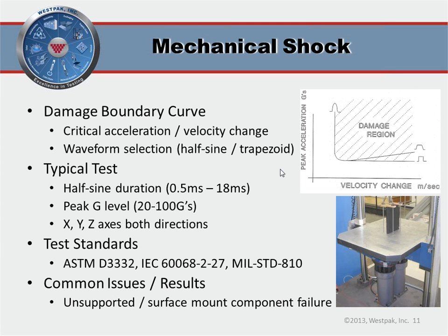That's cool. Mechanical shock testing is normally conducted on a shock test machine, believe it or not. And there are two interesting and important components that we're looking for in mechanical shock. One is what we refer to as a critical acceleration, and one is critical velocity change. So let me explain those two. Critical acceleration is simply multiplications of Earth's gravitational constant, and those can build up during an impact as a result of basically the change in velocity of those things.